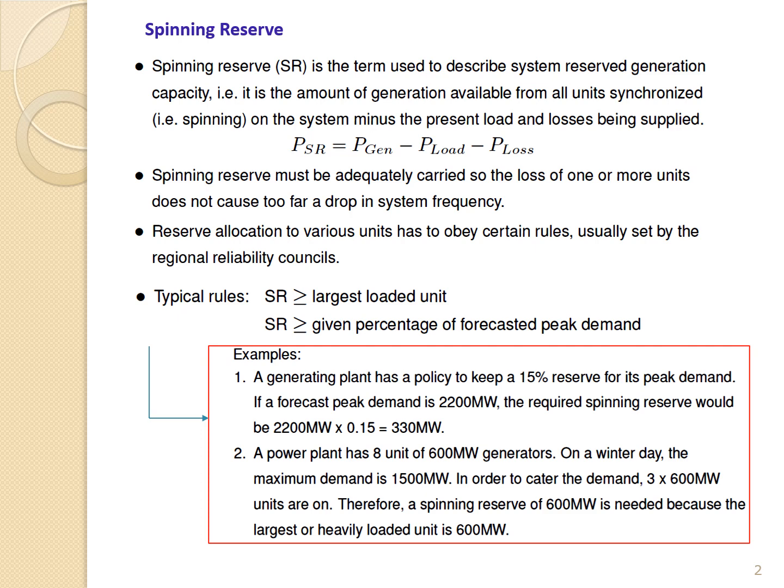Similarly, all the units which are supplying a given load demand are not running at their maximum capacities, rather they have some margin available with them. This margin can be calculated in total to know the total spinning reserve capacity available with the system, and this is particularly important in case there is an increase in the demand. This extra margin or reserve will be fed to the network to meet the new load demand.